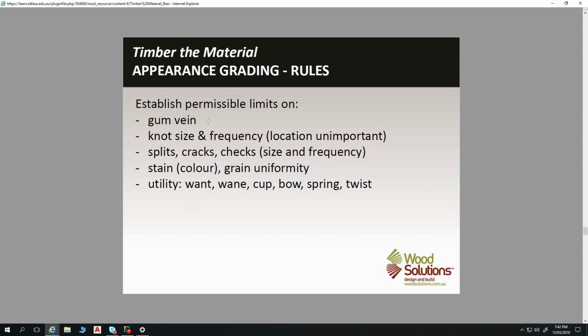But sometimes you find these, like a dark section that quite often is on a curve like that, and there's a little piece missing, and there's all these little bits of sappy stuff in the timber. That's what's called the gum vein. And in those hardwoods, particularly like jarrah, it provides no structural support in that area. So you have to be aware of such things.